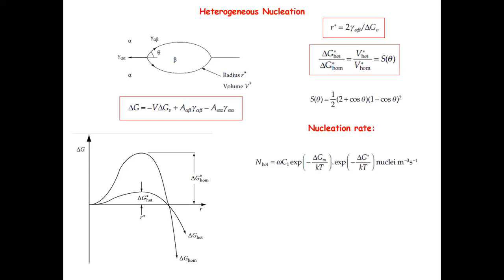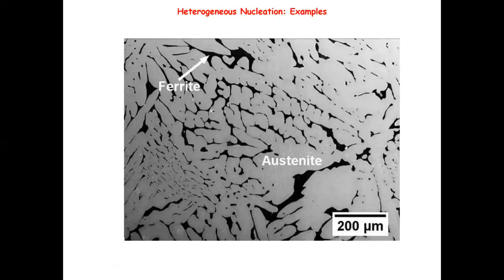So, for the same consideration, we have the nucleation rate. The key factor to determine the nucleation rate is this term, the critical energy barrier. If you take the ratio between the two, you'll see that the nucleation rates for the two cases are related by an exponential factor, depending on the difference between the barriers for nucleation.